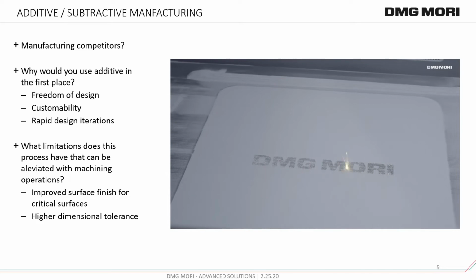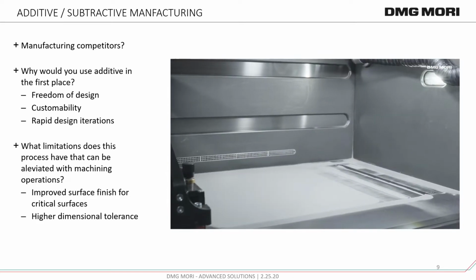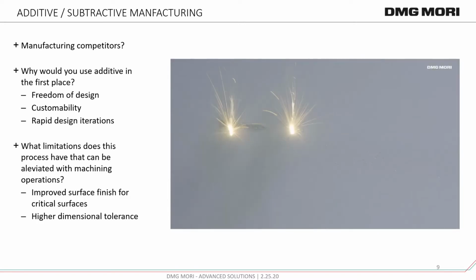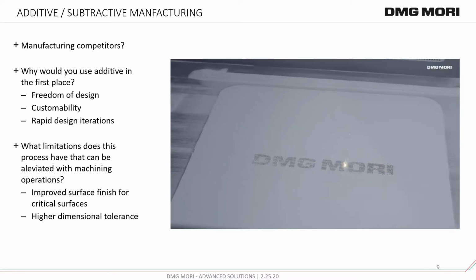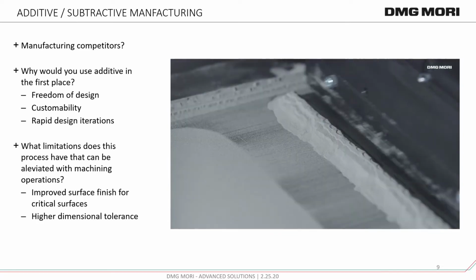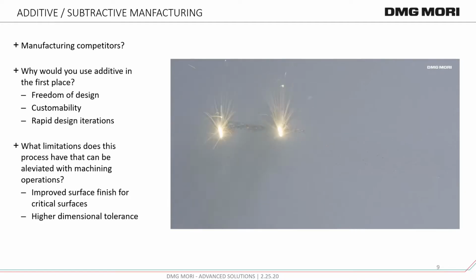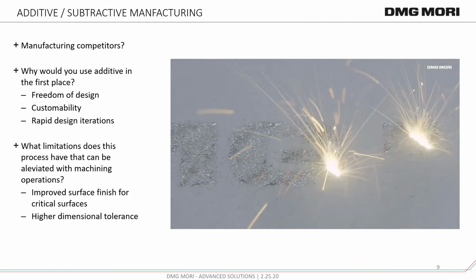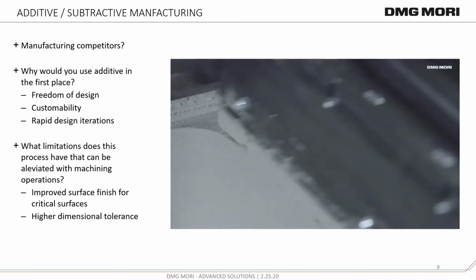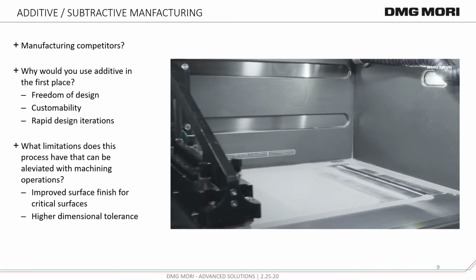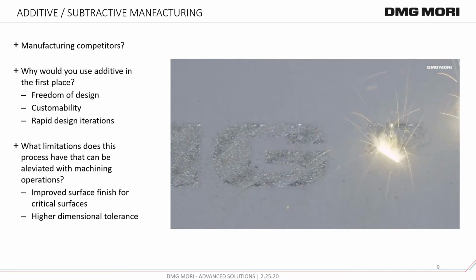Additionally, within the manufacturing process, you don't need to do any sort of CAM work on the front end to create a toolpath for your part. So it's a lot easier to make changes to your design and then bring that straight to your manufacturing floor. And what that does is it allows you to get very rapid design iterations done to just increase the overall speed of your R&D for a new product.